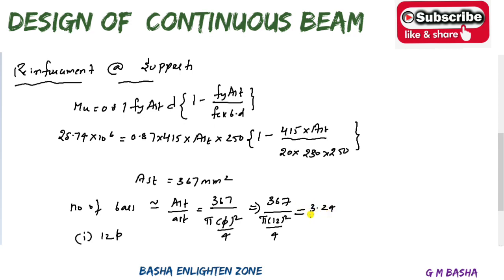It is not possible to keep that value like that only. Go to the next number, which is 4, and check the overall area of the steel obtained if you keep 4 bars. That is 4 into pi 12 square by 4. Why? Because we chose the 12 bar. If you check with this condition, your area of the steel will be around 452.16 mm square.